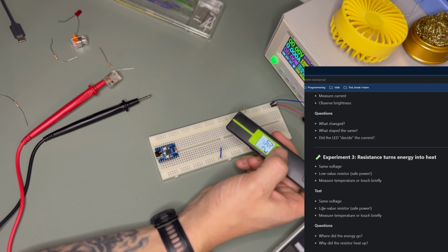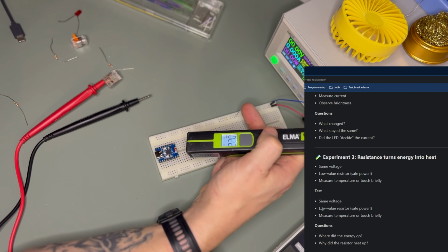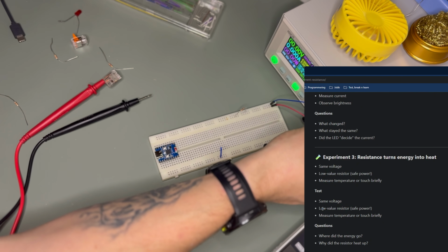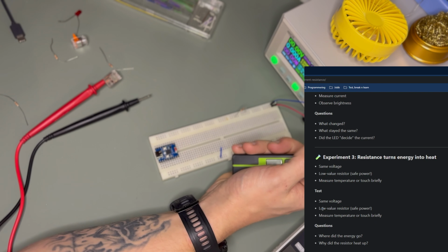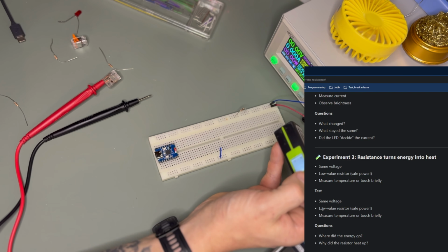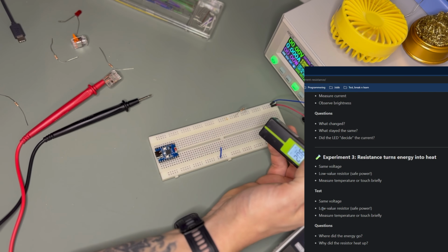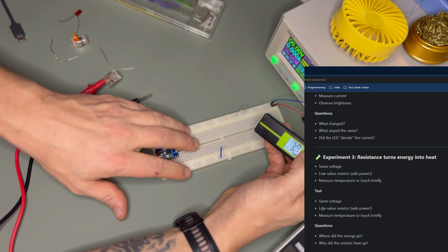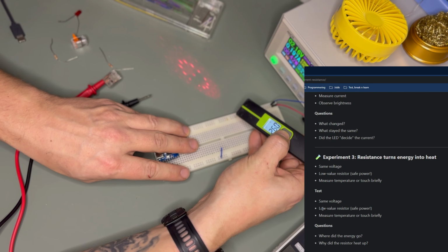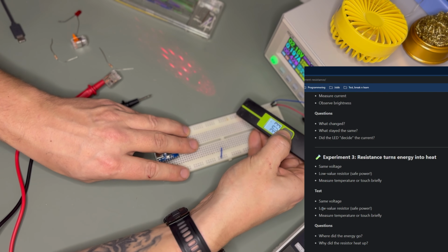Okay, so we're going to power this on and measure the temperature. Maybe it will burn. I can set the power to maybe 200 milliamps maximum, and I will try to touch it. I will measure first, just to see how hot it gets. So here we go. It draws 200 milliamps right away. 26, so it gets hot quick. It's hard to get an accurate reading with this one because there are a lot of points, but 38 degrees. I will just turn it off here.